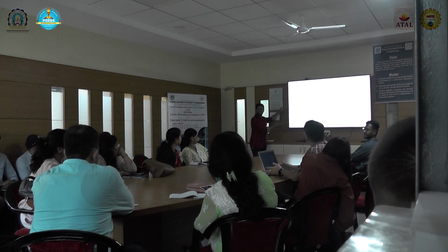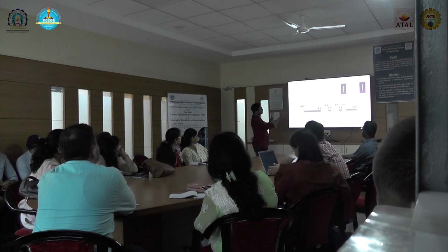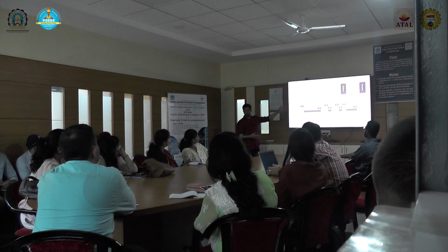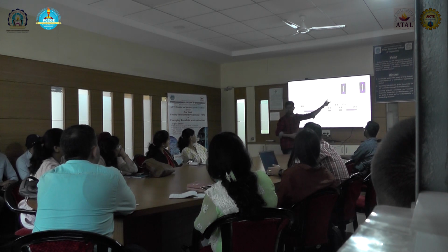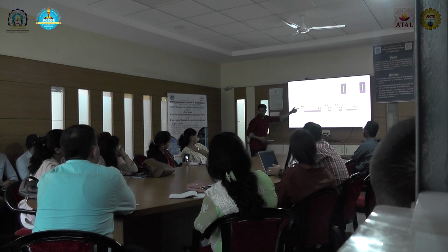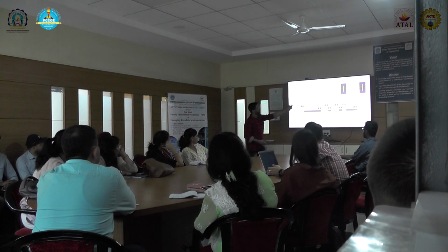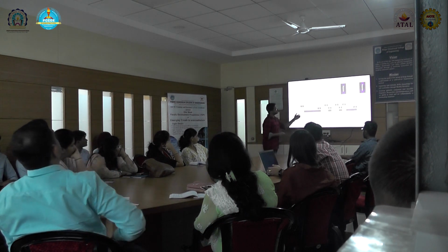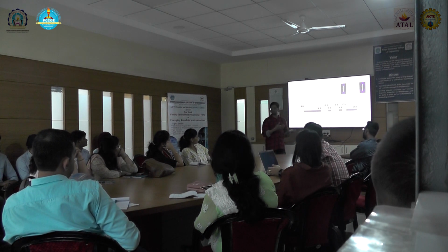Understood what the interface is and how req, done, and busy work? Okay. We'll move to the protocol. Here I'm trying to explain req, done, busy with a simple waveform. We will consider the requester and the responder. The requester is going to request the responder, and then we will get the request as high. Once the request is high, as I told you, the interface gets busy. So busy will stay high until we get the done. Once we get the done, the request is completed and busy will get low. Similarly, 2 and 3 indicate how early we can get the req done handshake.